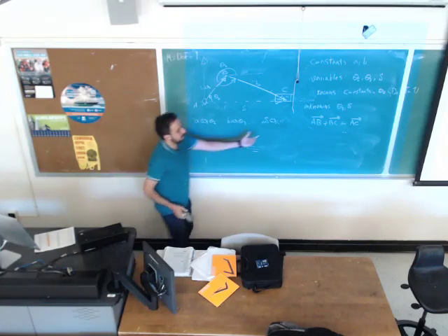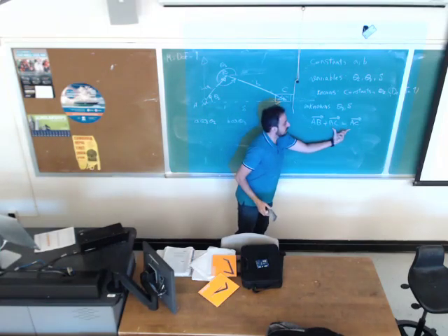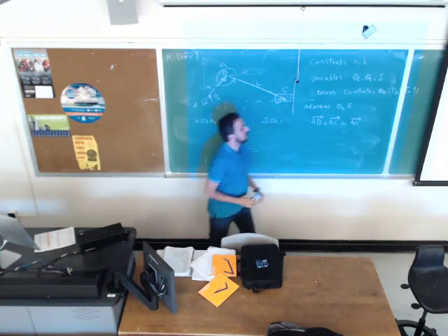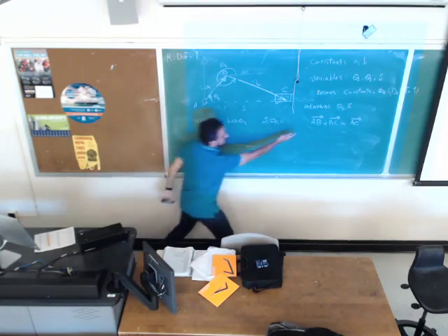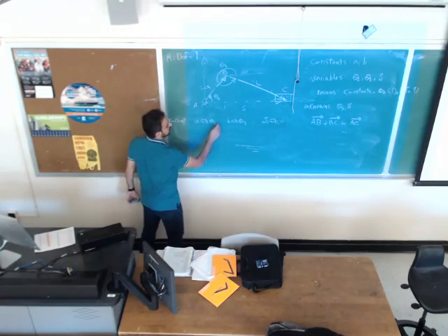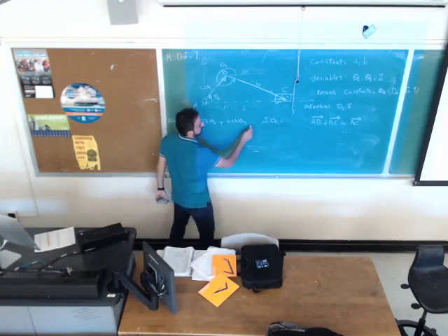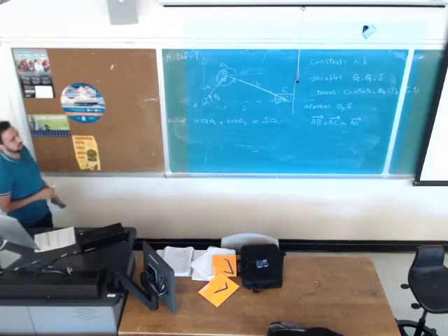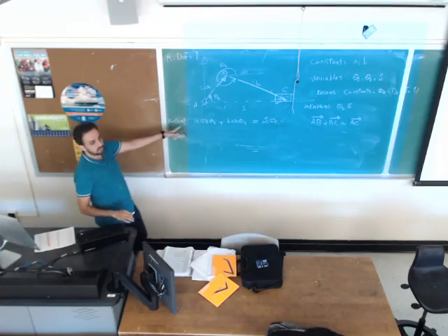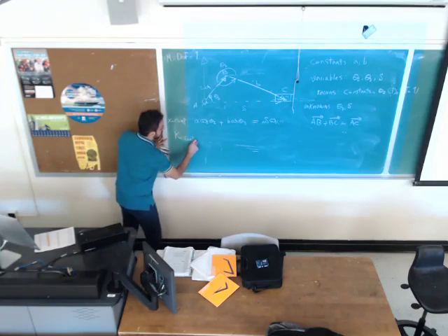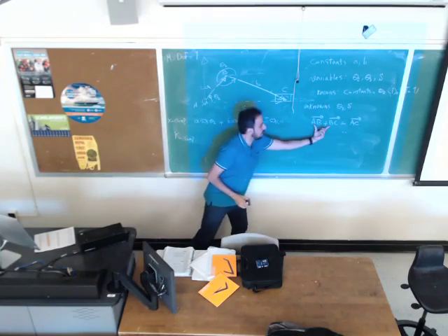So now, if I'm looking at this vector loop equation, it says vector AB plus vector BC should be vector AC. If this is true, for the x component of this equation, it should be true. So A cosine of theta 2 plus B cosine of theta 3 must be equal to S cosine of 0. Good? So Y component, I'm writing this equation for the Y component.